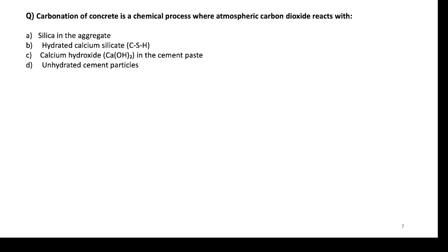Okay, let me tell you what is the carbonation. First of all, carbonation is the reaction between the CO2, which is present in the atmosphere, and concrete pore solution where there are some ions present. When CO2 enters into the concrete structure, initially it dissolves in the pore solution of concrete, forming carbonic acid, and then it reacts with the ions and hydration products in the pore solution to form calcium carbonate. That reaction is called the formation of calcium carbonate, which is nothing but the carbonation of concrete.